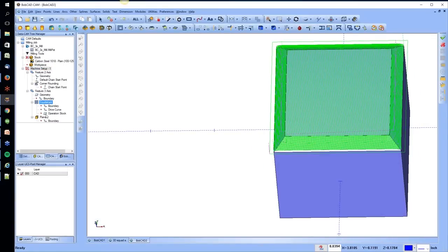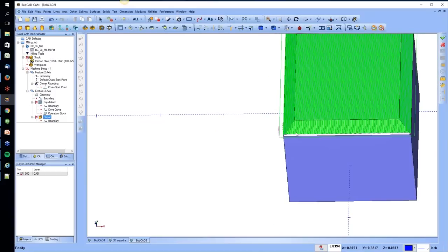All right, let's go ahead and blank this out and this out. So planar, as you can see, cuts across. It's cutting unnecessary area because that's what it's designed to do. It's designed to go in one direction across, and you'll still get the chamfer. You're just going to have some wasted area. Now you can go in and try to boundary it off, but what will happen is it'll just keep cutting like this, staying here.